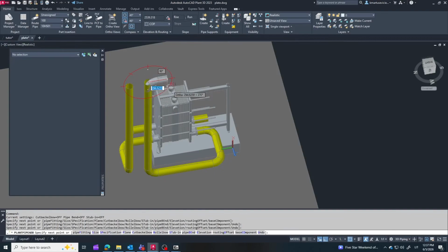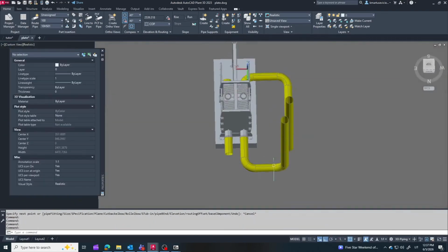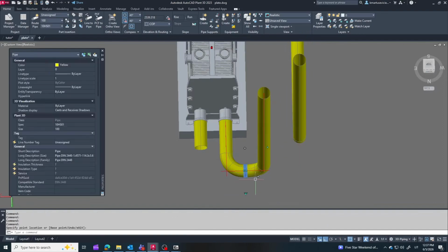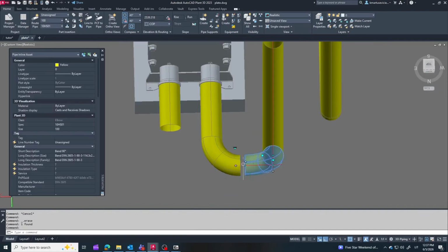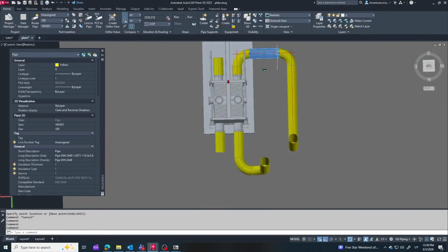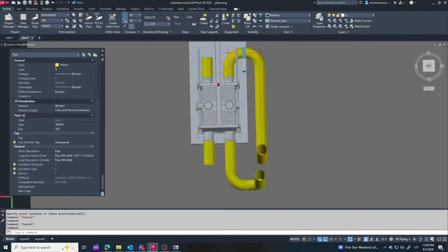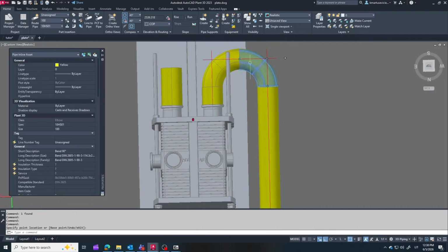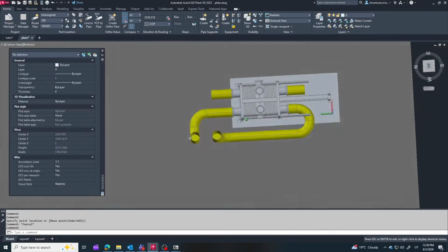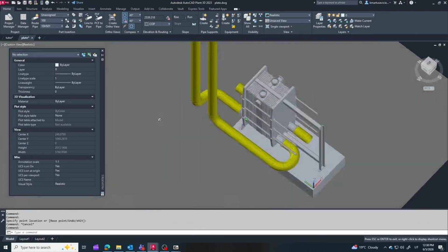When routing these lines, you always need to plan ahead for ergonomics and maintenance. Make sure every single valve is easily accessible and not buried behind other pipes. I also focus on maintaining a clean piping order. Avoid creating unnecessary loops or U-shaped lines. Those pockets trap fluid, cause airlocks, and make draining the system a nightmare. Keep your runs straight, logical, and clean.